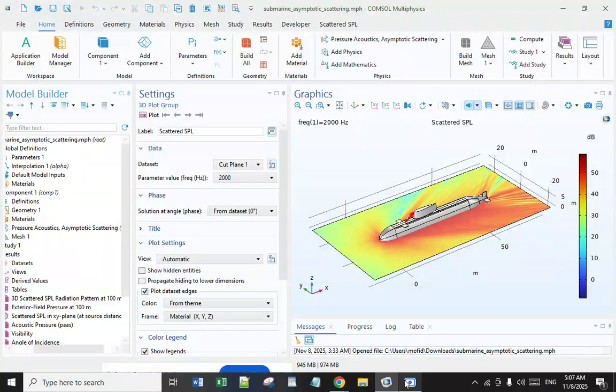with experimental data. Furthermore, the model is resilient with small functional fluctuations in the scatter SPL of the submarine seen under various parameter settings, proving its usefulness in mimicking the submarine acoustic behavior.